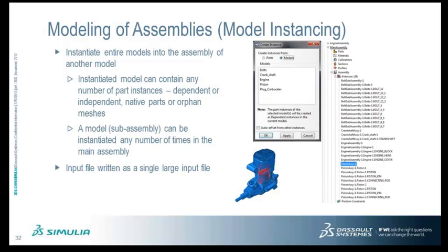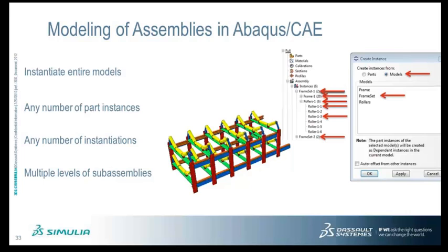If you go to the next slide, Dale. Of course, you can see that this capability is useful in general, but it's particularly useful in the example that we've shown here, which is that of a conveyor belt which contains a series of repeated frames. So here you can see each frame being a subassembly in itself, and we've instantiated that frame multiple times to create the overall assembly hierarchy. I must also point out that any changes that you do to the base part of the base assembly that's been brought in to build up your assembly would get propagated automatically.